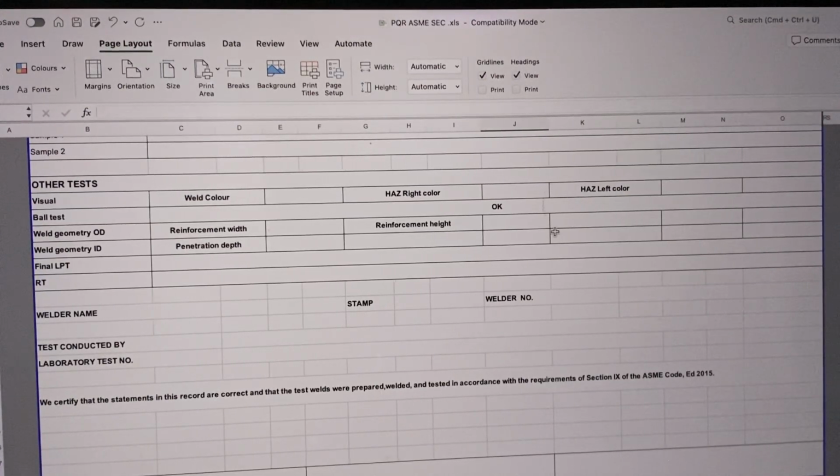We are going to measure what is the bend the PQR plate had. If the PQR plate bends, then you will not be able to take your specimens, so you will have to use corrections, whether that correction was done by welding, by heat, or by mechanical force, replacing it under the press. So how have you corrected it, and what was the bend angle? Was there a distortion in the longitudinal side also, or only transverse? And if it is a pipe, whether there was a shrinkage in diameter, and whether the overall length also shrank because of the shrinkage in diameter, distortion.